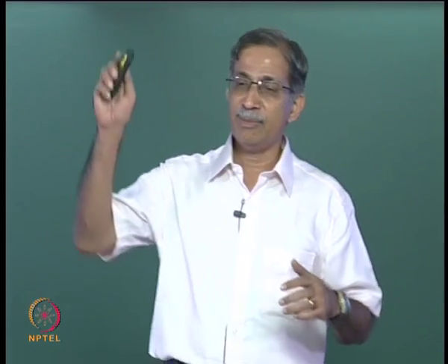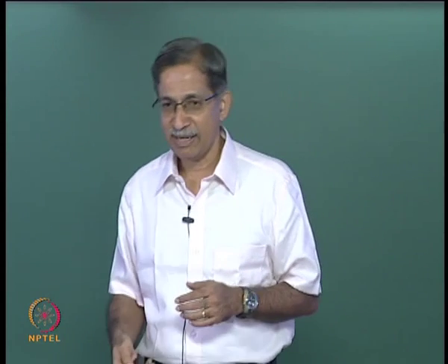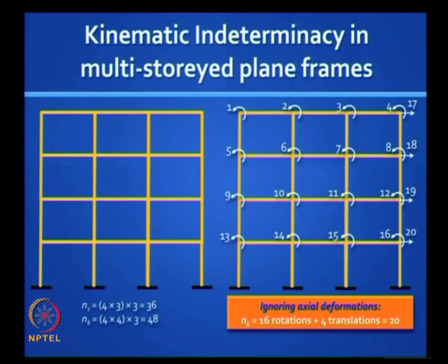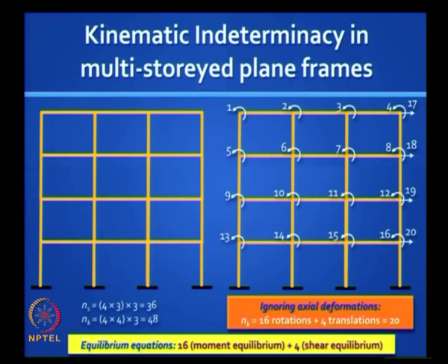okay? And there are serviceability limitations in a tall building, the maximum drift in the building should be limited. Okay, usually it is height by 500 under lateral loads. Okay, so can you analyze a frame like this? Exact solution? Yes, that is the idea. We want to be able to handle any structure, any skeletal structure of any shape subject to any loading, including indirect loading. Okay, that is the objective of structural analysis.